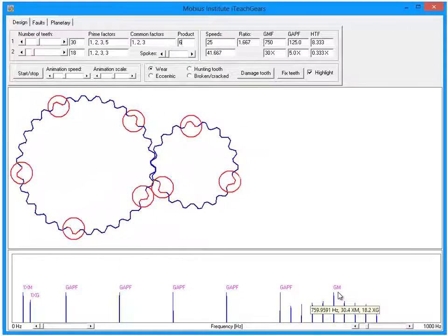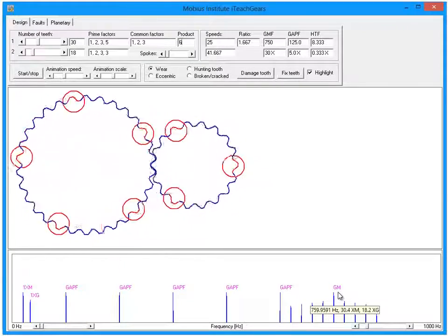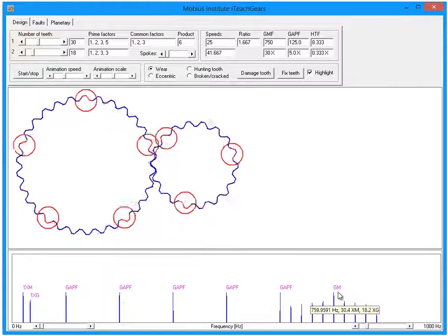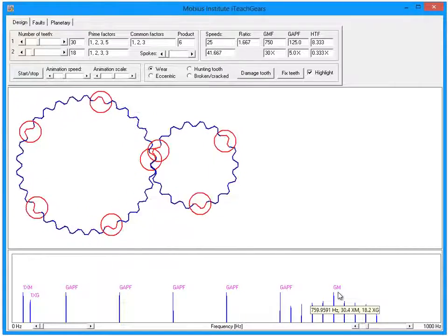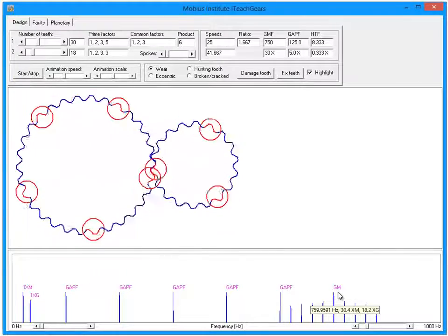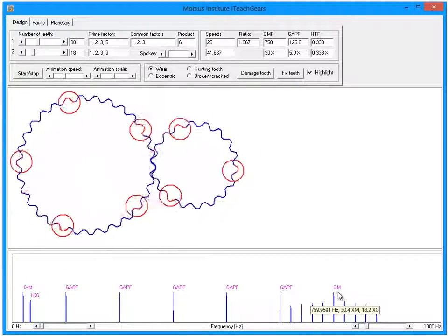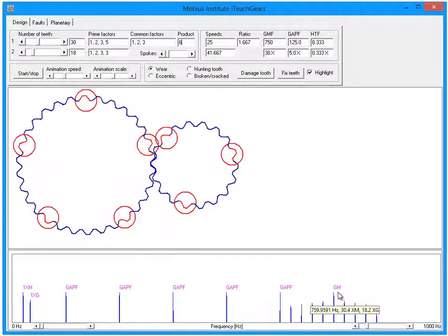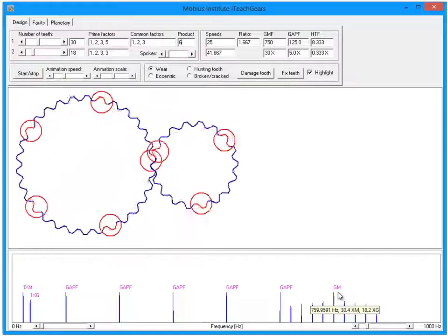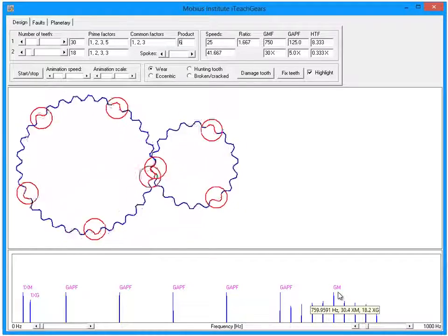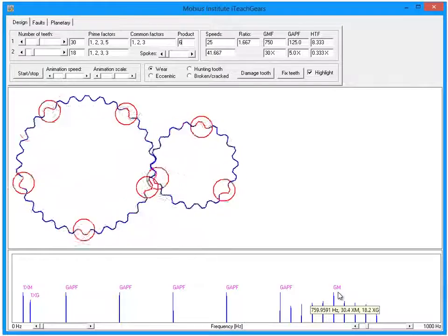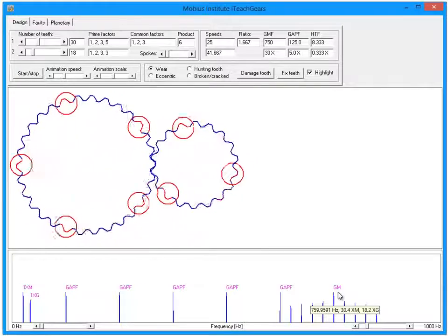The point is you can see these peaks. Now, as I said, ideally a gearbox will be designed with a prime number of teeth. But if there's a specific design that was required, there may not be a combination possible with prime numbers. So they have to use these non-prime numbers of teeth, and therefore this is a source of vibration that you may see.